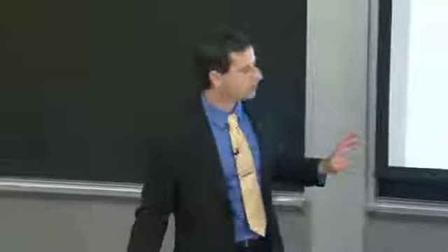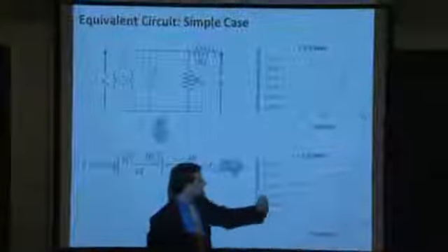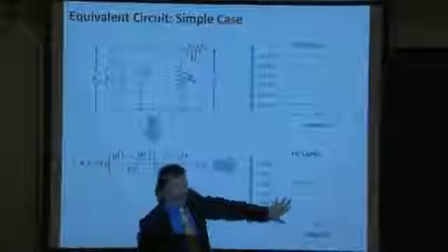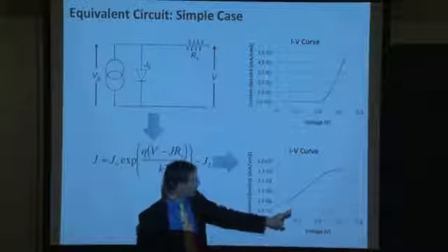And so when you test the solar cell devices, typically the IV tester will measure the shunt resistance in a solar cell by looking at what's happening under very small bias conditions right here and comparing it against the healthy cell that it would expect.